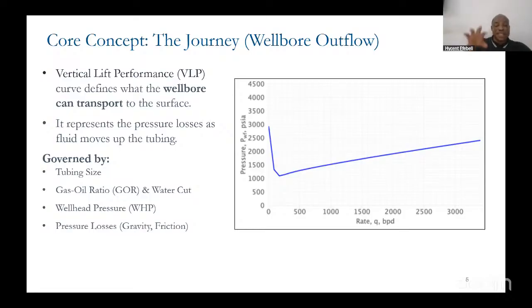You know, water is heavy. The density of water is higher than that of oil. So as water is increasing in the wellbore, the overall density of the fluid stream is increasing, so you need more energy to move it from the wellbore to the surface. Then your wellhead pressure is like a load. You need to overcome it to be able to produce into your separator.